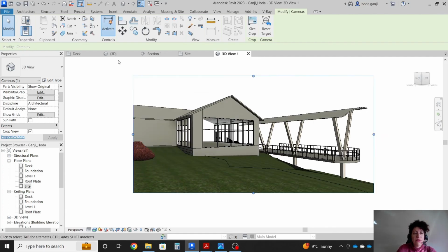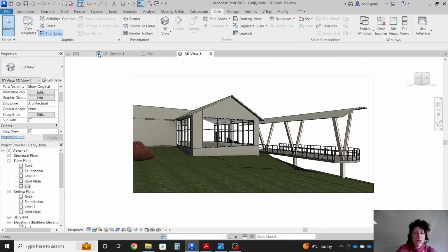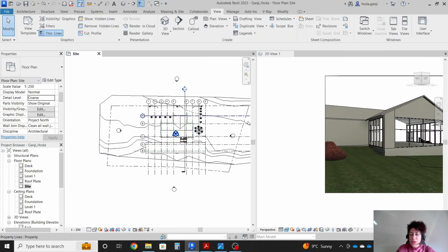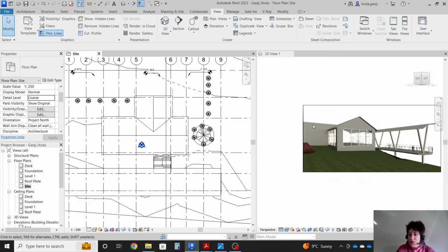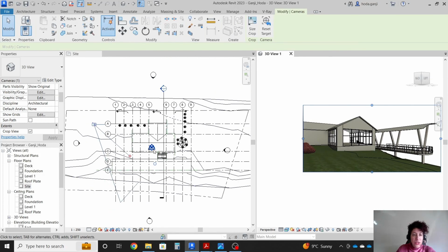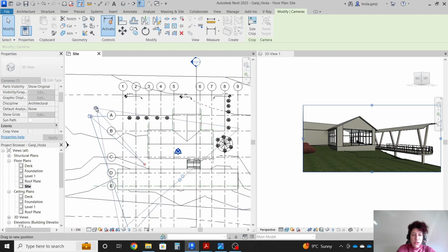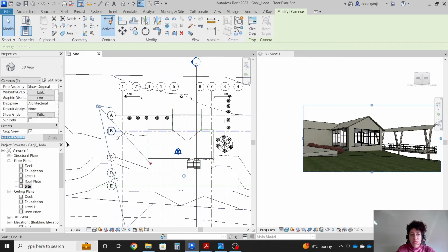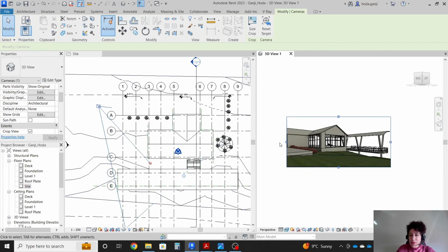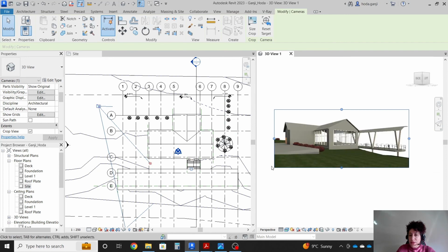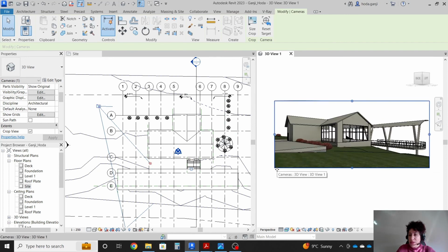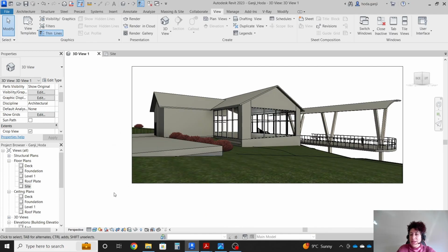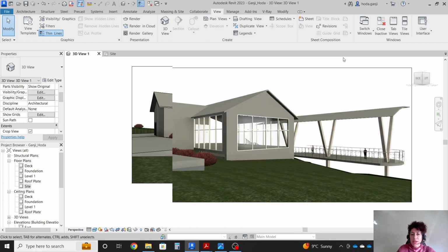Okay, just for your information, if you want to adjust the target of the camera, I want to go with WT, so the site and the camera are side by side. I can select the edges here, and let's say maybe the camera, I want to move it a little bit, and I want to move the target a little bit like this, and maybe I can also move this a little bit further. So this would be probably not a bad view. I want to go with TW. You can render it. You can render it in Revit or anywhere else.